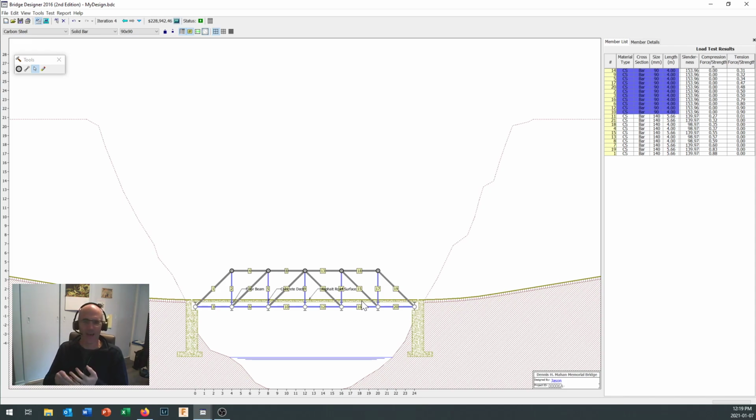We'll talk more about that in the famous Galloping Gertie, Tacoma Narrows Bridge, a little bit later on. But the wind load on a bridge is probably one of the major live loads, more important than the vehicles, actually. For a mid-sized bridge like we're talking about in here, certainly if you're planning to have heavy vehicles go across it, the live load does matter quite a bit.